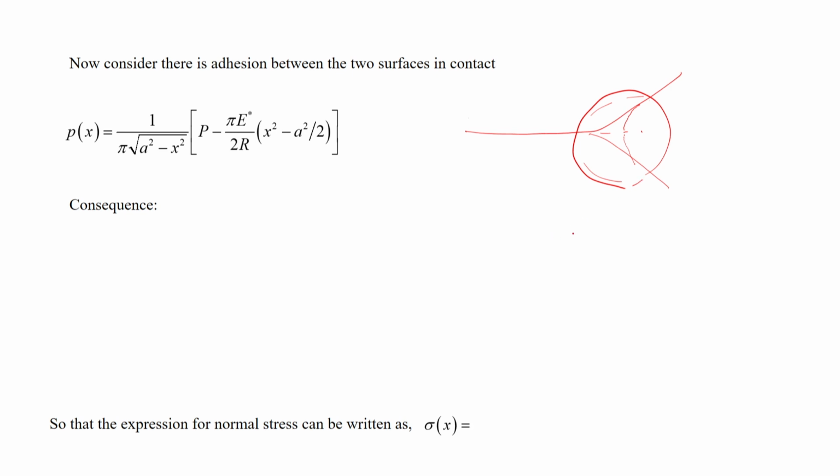What they do is find out the stress around a crack tip. So this is a crack, let us say, two materials being opened like that. This is one material, this is another material, and they apply some load over here to open it. This kind of crack opening situation they call a mode 1 crack.